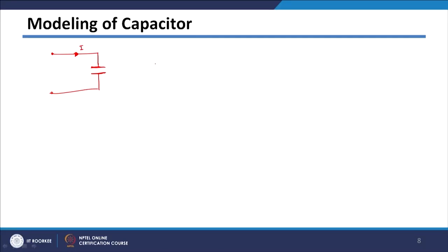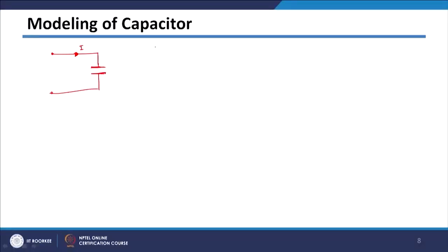To calculate this current, the capacitor will act as a constant susceptance device. So, we need to calculate the susceptance from the rating of the capacitor and then use that as a constant, and then in each load flow iteration, depending upon voltage, the current will be calculated. In this case we know that any impedance of the system will be calculated by kV square upon MVA.